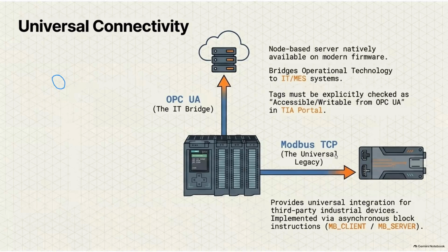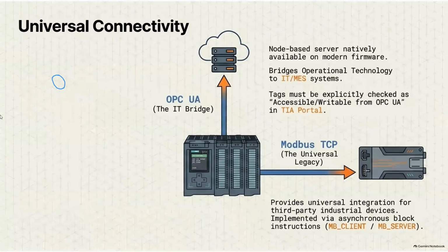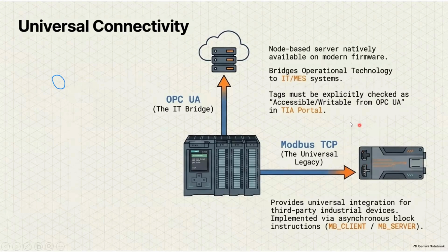They only have Modbus. With Modbus, a single cable will be laid to all such devices, like the 10 devices, and each device will be given an address, and there will be an IO interface module.